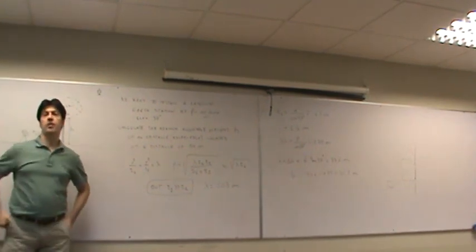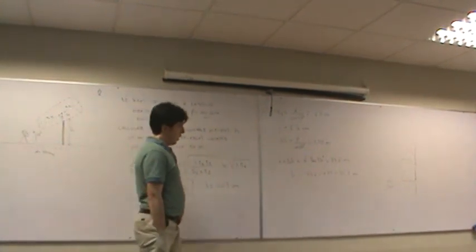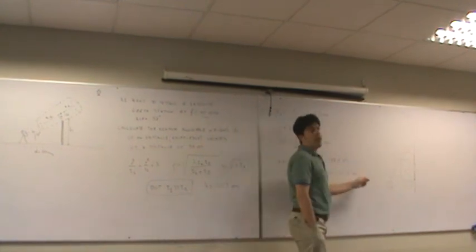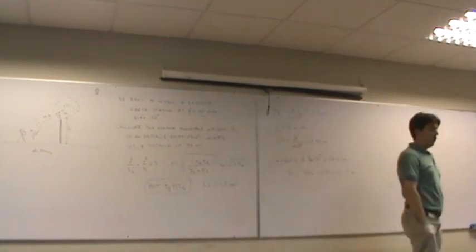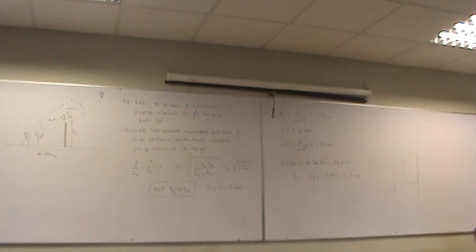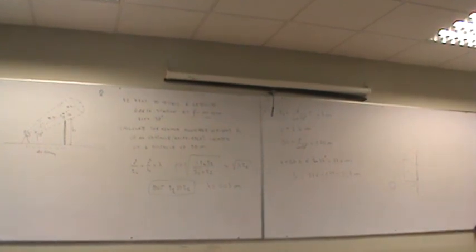In practice, you want to leave an extra safe margin, because you want to keep free also the second and third Fresnel zones. But this gives you an idea of what is the region in space that you have to keep free from obstacles in a satellite link.